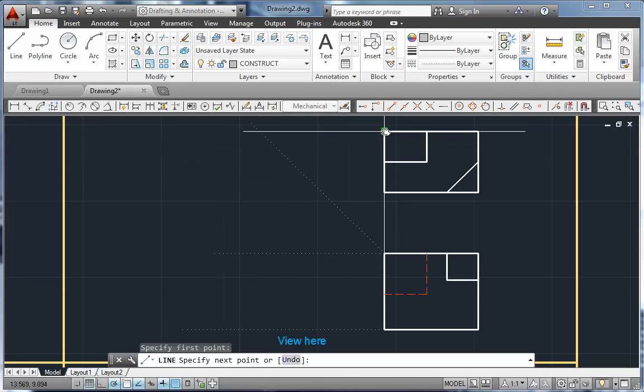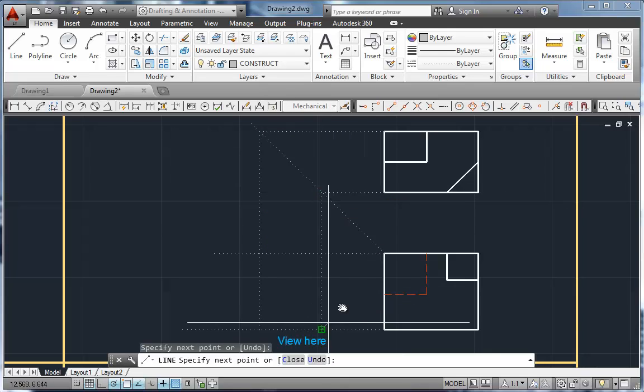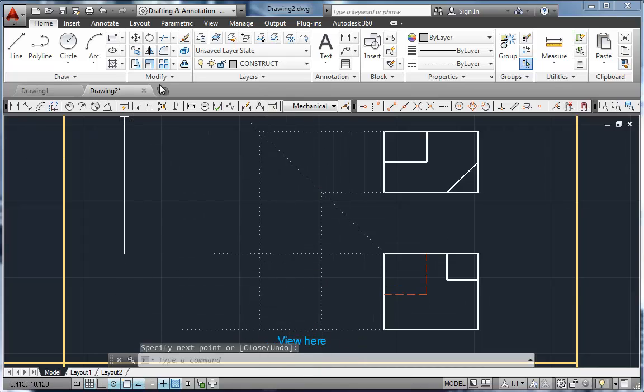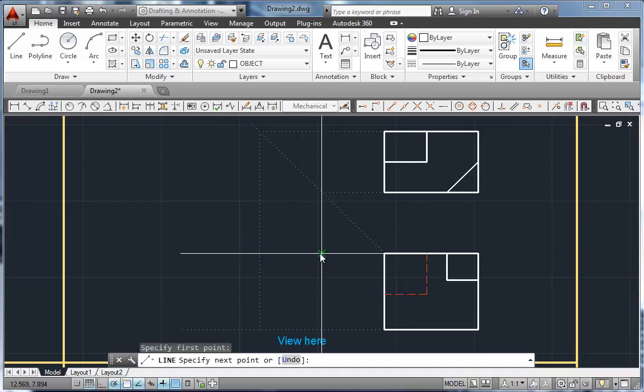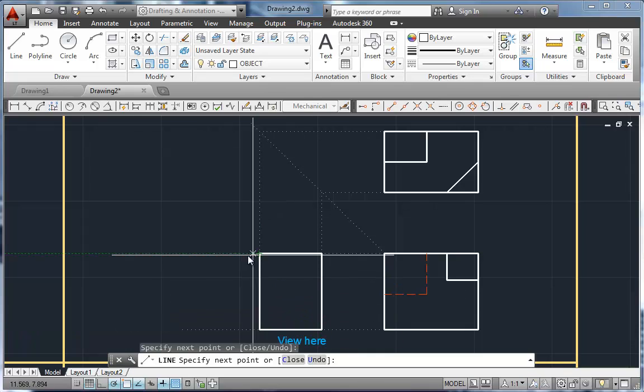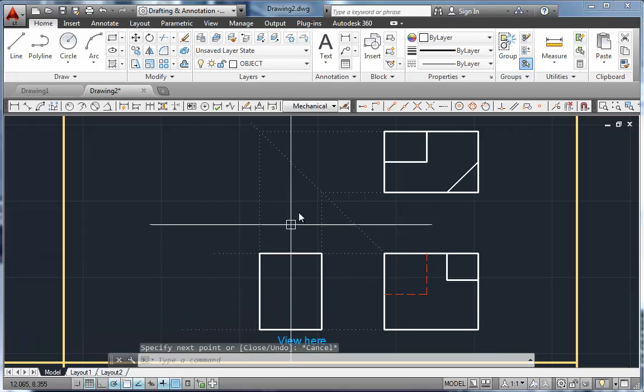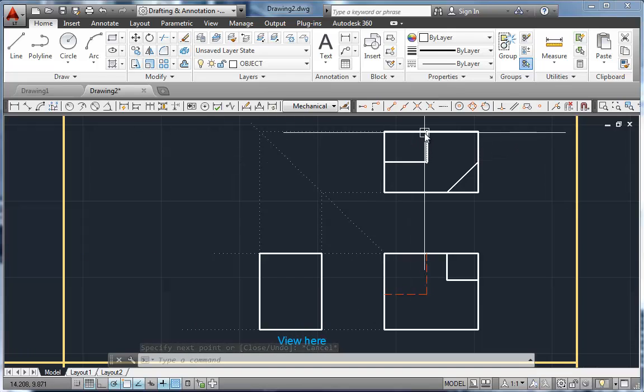Now I'll draw some lines, and we'll just take the depth across to begin and down, and then the front edge over and down. Here's my front view. I'll go ahead and draw some object lines over the top. So I'm going to switch to the object layer now, and we'll draw some lines, and I'll just snap right over the top of the construction geometry, like so. All right. I'm seeing a pair of lines here that tells me that I have either the edge view of a plane or an intersection between two planes. And I have what looks like a planar surface right here.